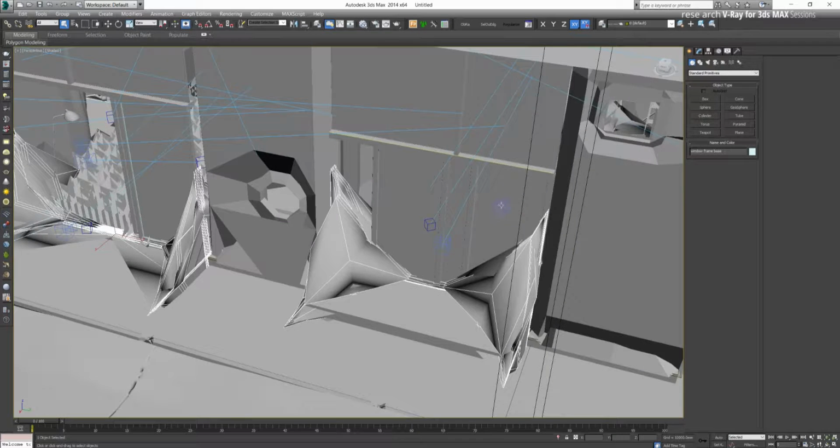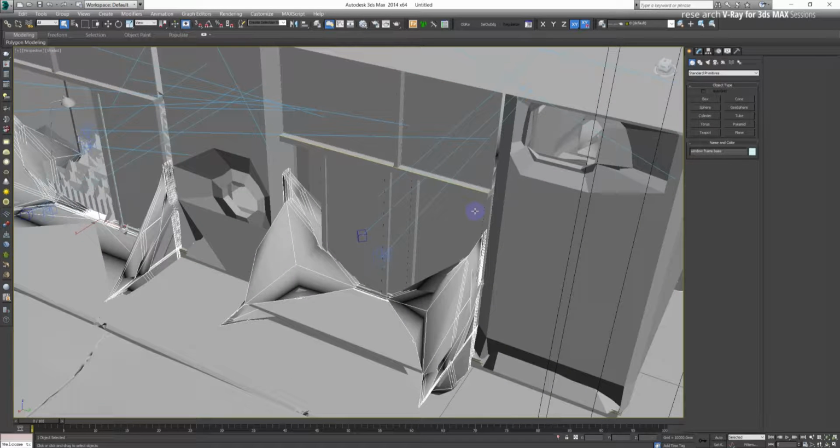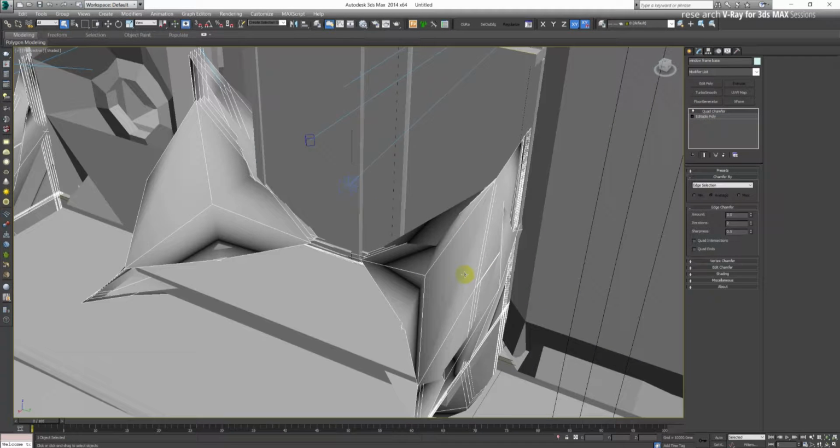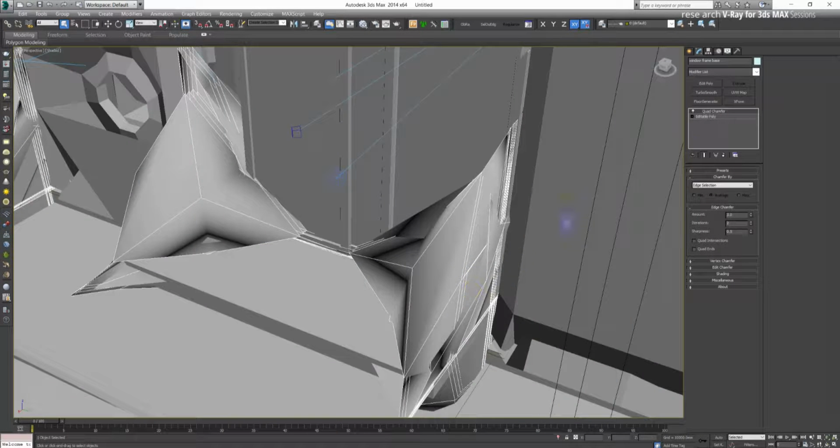But for some bit of troubleshooting, if everything was baked, if all the geometry was baked, nothing would happen. The model would be done just fine. But from the moment that I'm using, for example, quad chamfer, quad chamfer is by default and by its own algorithm using millimeters. So it's being scaled up. So everything else is done correctly. Just quad chamfer.